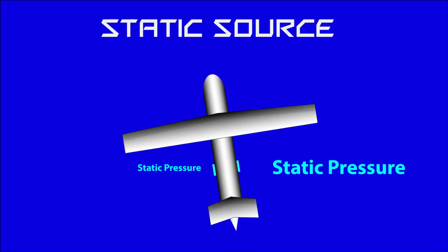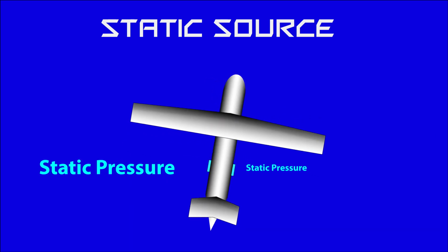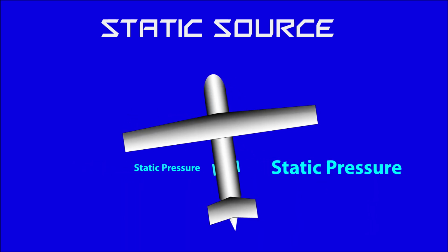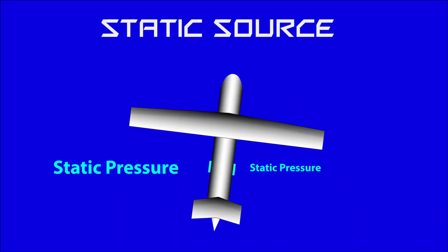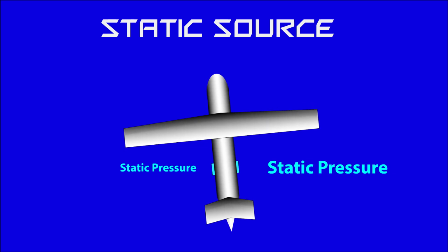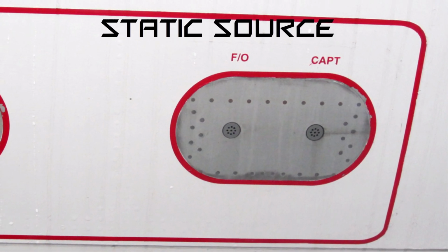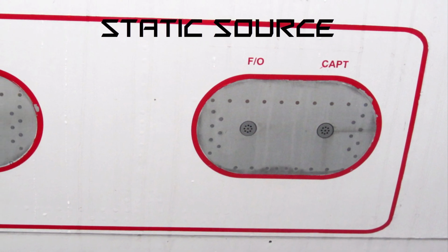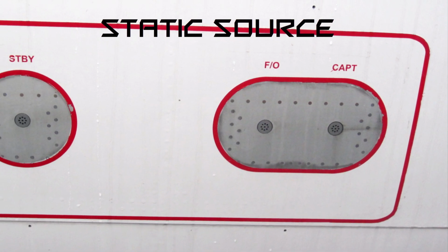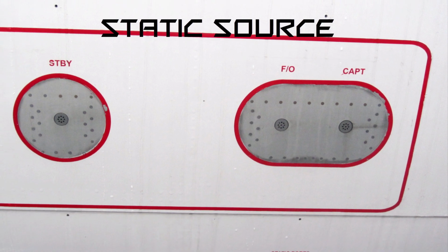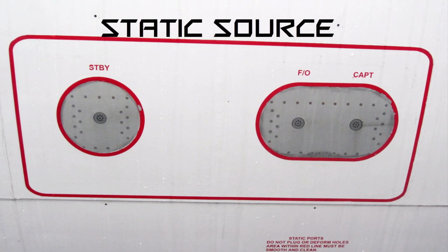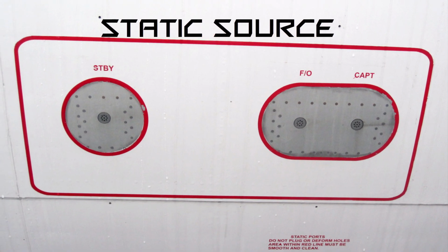The purpose is to even out any differences of pressure that are caused by the sideways motion of the static vent, which occur during a yaw or side slip condition. If a failure of the primary pitot or static pressure source should occur, introduction of error may occur in the instrument readings. The installation of a standby system in some aircraft acts as a safeguard against partial failure.